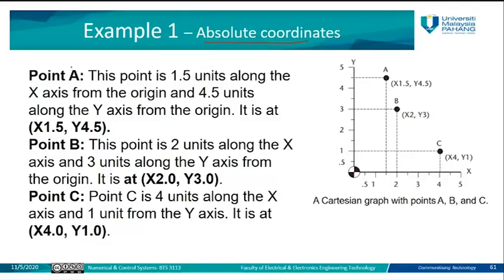Now, if I ask about the point A here, where is the point A? It is here. What will be the coordinate for point A, and how can we program this coordinate into the machine later on? After we define the absolute coordinate, we give it G90, for example, it is absolute coordinate. What is the movement on the x-axis? What is the movement on the y-axis? Since I have only two axes here, x and y, how can I define the coordinates?